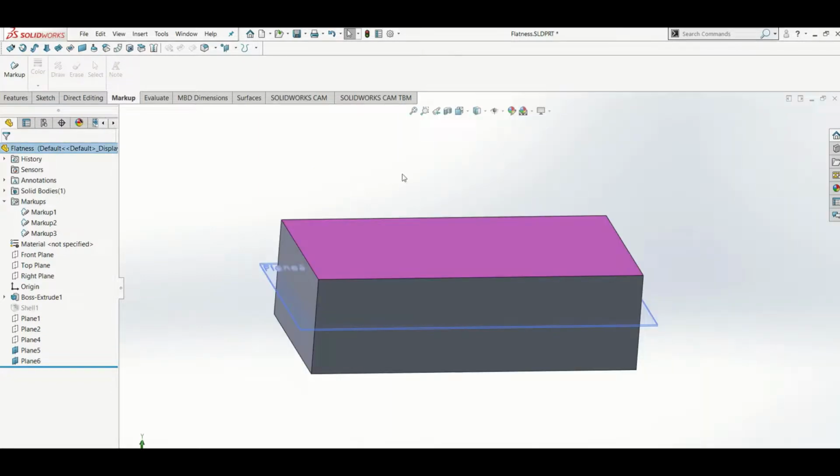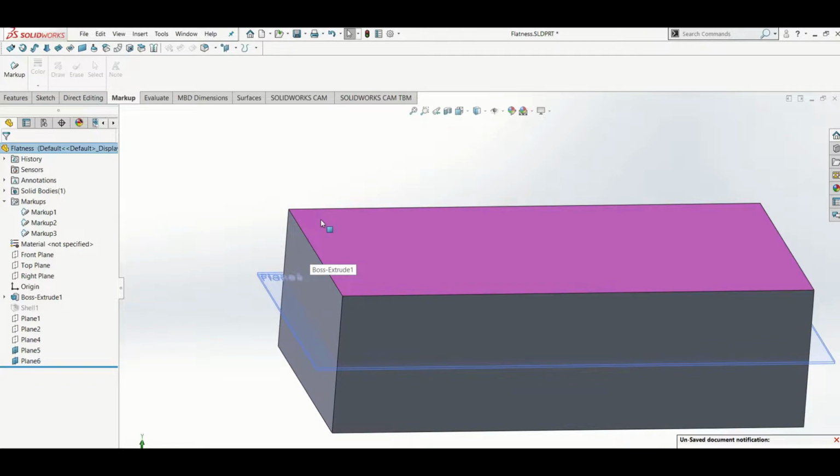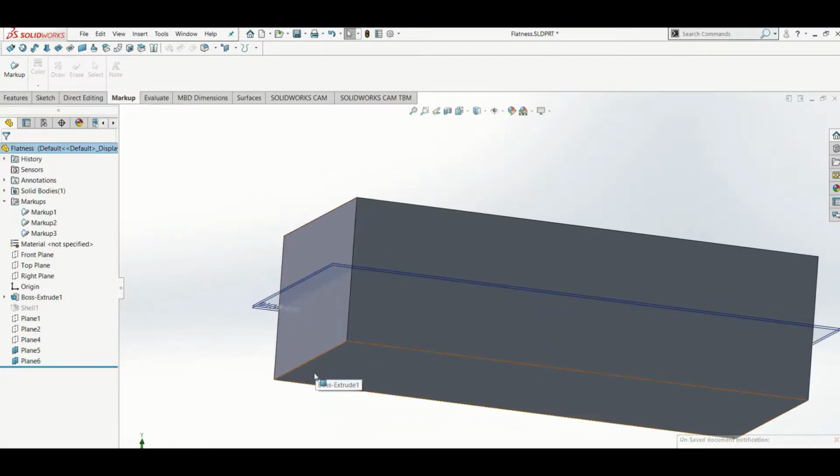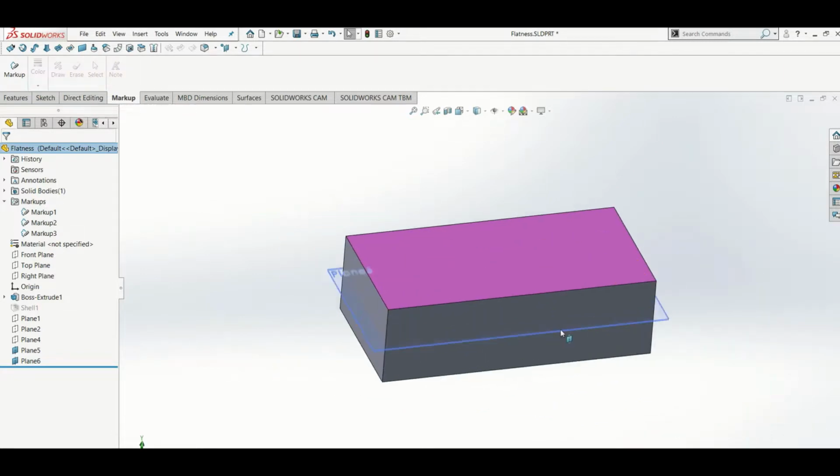For measurement, you can put down your probe on the top surface at this point, then shift down to the opposite side of the bottom surface. We can repeat the process all over the surface until we determine the derived median plane. Until then, we can check if this center plane can lie between the tolerance of 0.1.